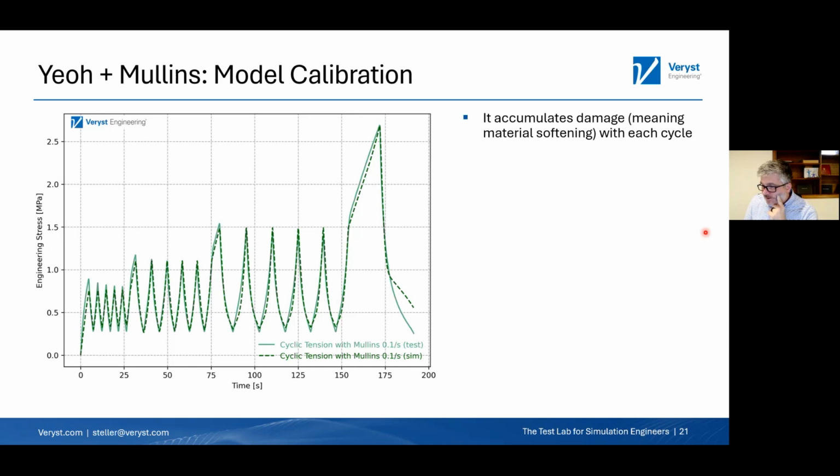Which tests are needed to calibrate the TNM model? I would test in tension and compression, multiple strain rates in one of those modes, with some cyclic loading. Can the models be hooked up to the testing in a digital twin fashion for the calibration? I think so. That's a very broad question, though, so I need to know a little bit more.